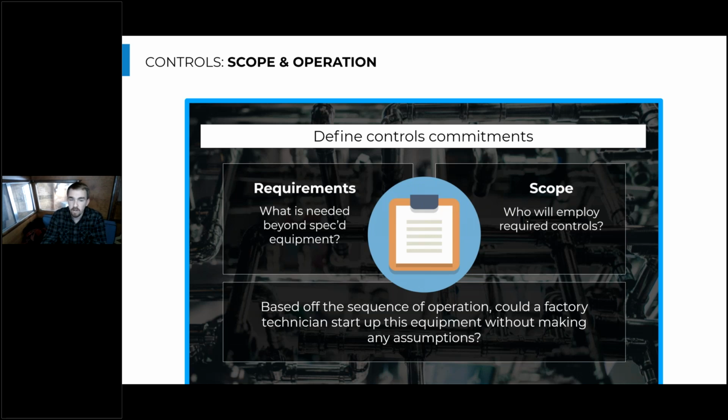So do we know who's actually going to put that in, and if they understand the sequence of operation for these heat pumps? And a key question to ask yourself before installing this system is, based off the sequence of operation, could a factory technician start up this equipment without making any assumptions?